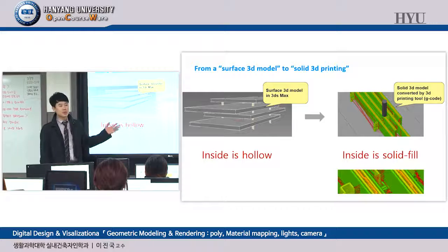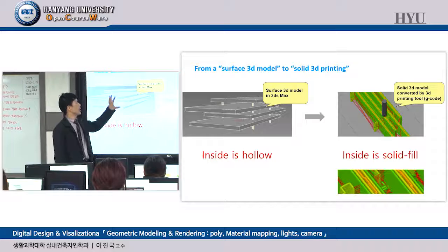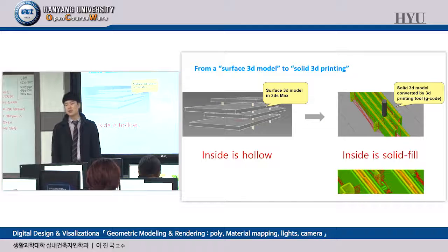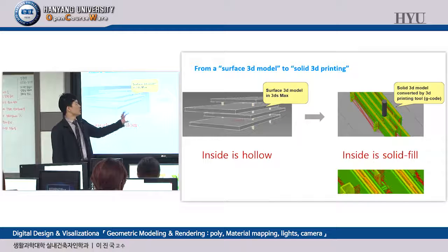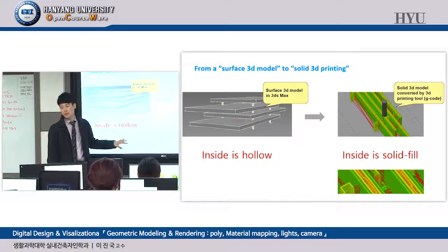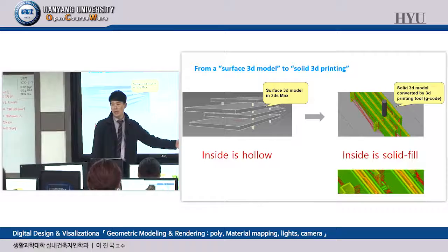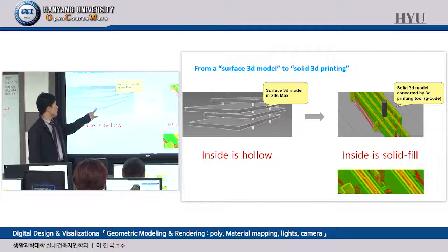But when I used this kind of 3D printing tool around 10 years ago at Georgia Tech, I couldn't print this out in general 3D printers at that time because there was no such functionality. Autofill of the inside, okay? We had to use a solid 3D modeler, not a surface-based 3D modeler. But nowadays, you are free to design with a surface-based 3D tool, and you can print this out without problem.